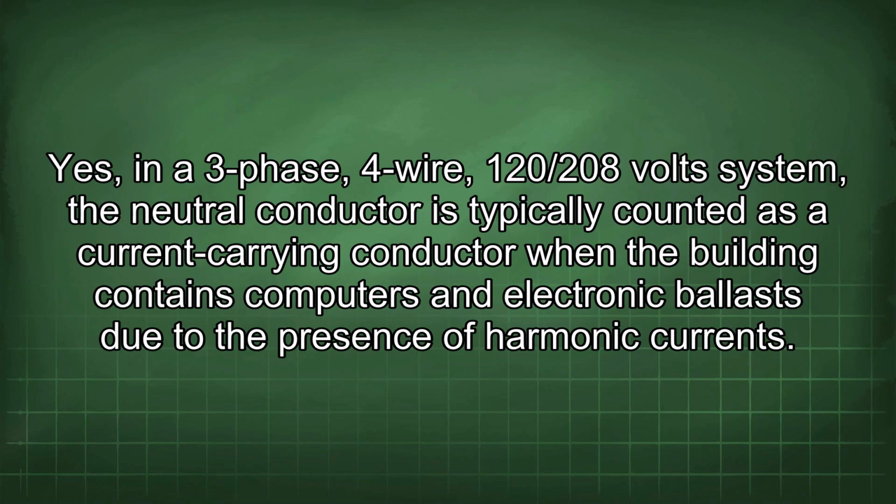Yes, in a three-phase, four-wire, 120/208 volt system, the neutral conductor is typically counted as a current-carrying conductor when the building contains computers and electronic ballasts due to the presence of harmonic currents.